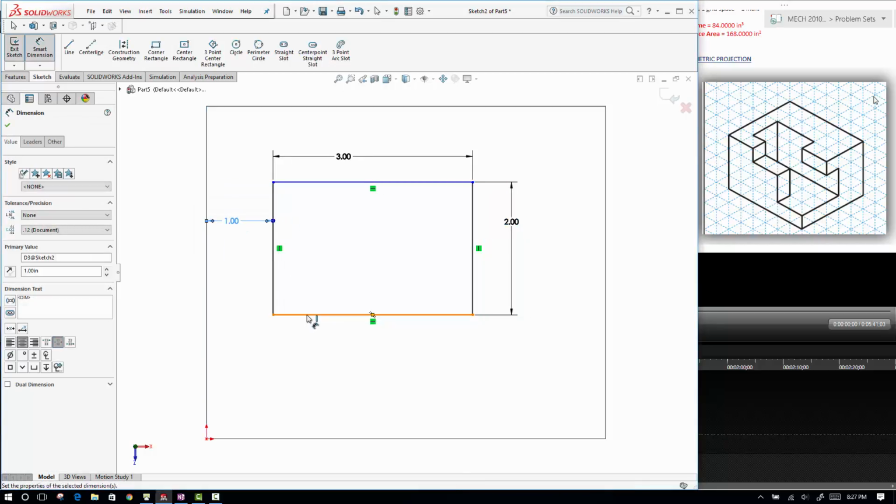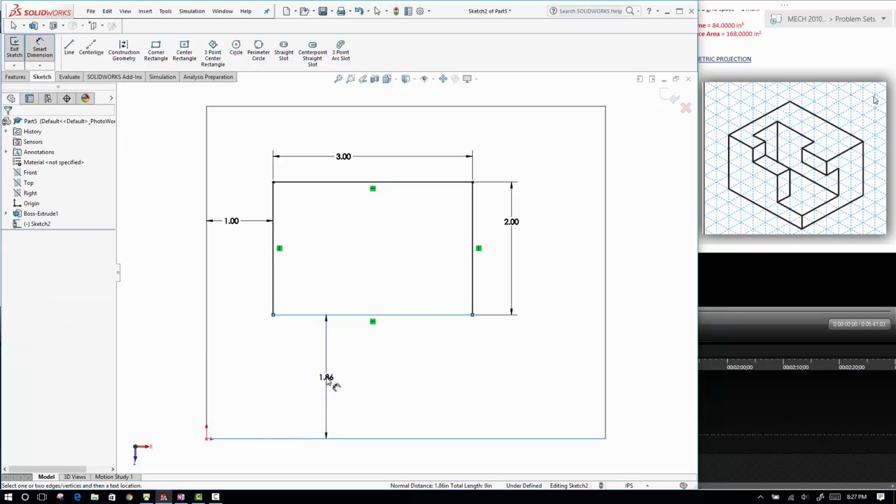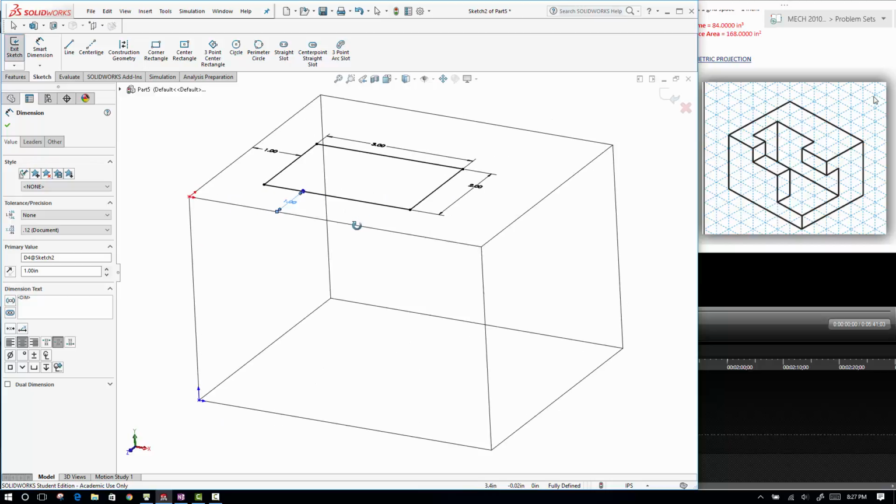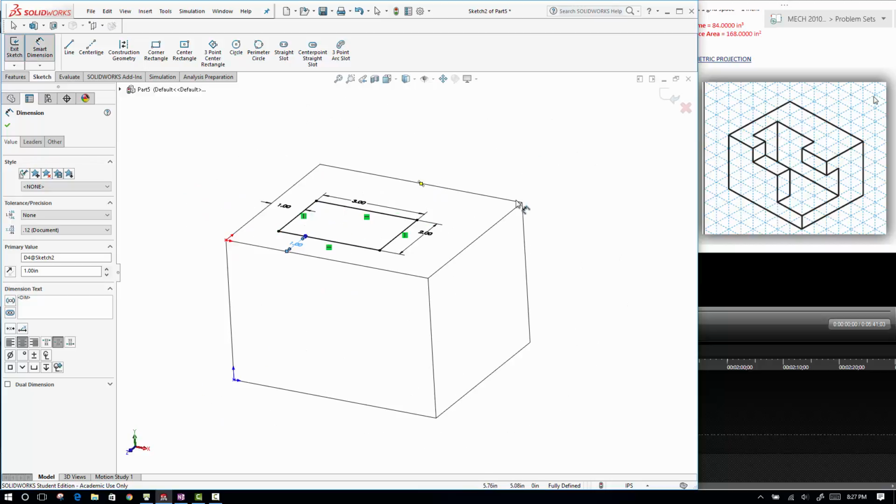Now while I'm doing this, I should mention that making a part like this, you can run into difficulties when you make certain cuts, that you will get errors to say that you're about to make a 0 thickness piece. So it can be frustrating, and you just need to be aware of what it is that you're trying to do. Sometimes you're trying to remove material that will completely remove a surface or an edge that's necessary for another feature. So I'll probably get into that in another video.